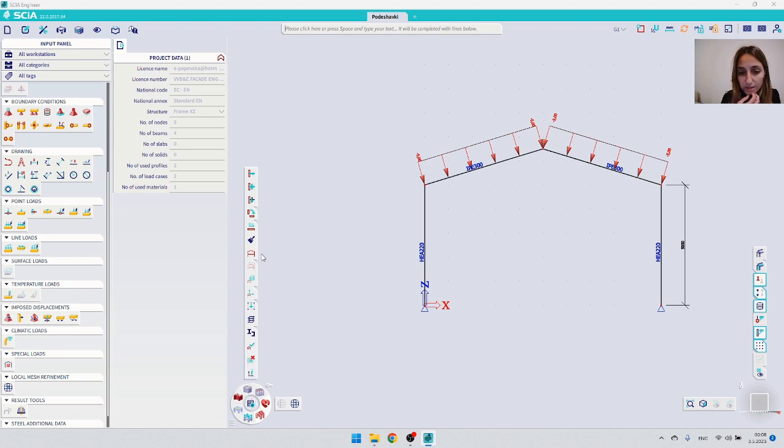Now the structure workstation and all the other workstations that are active in here are predefined by the software, but if you don't like some of the tools that you see in here, or you need to modify them, you can do that as well. So I generally take these two outside: I just click on one of them and start dragging it, and I put it on the top, in between the bin and the last tool, so I will drop it. Be careful, do not drop it in the bin. Then I go to the next one, I left click on it, start dragging it and drop it below. Now you can see that this is duplicated, so I don't need this tool. I will just click on it and drop it into the bin.